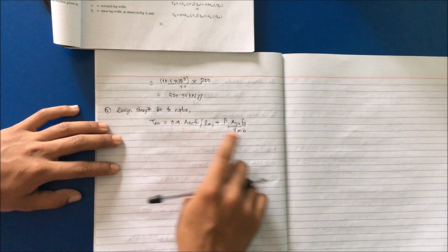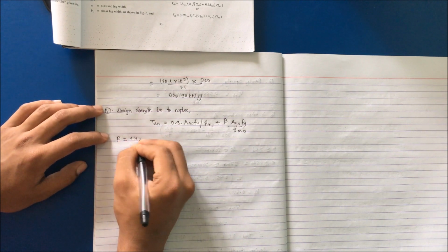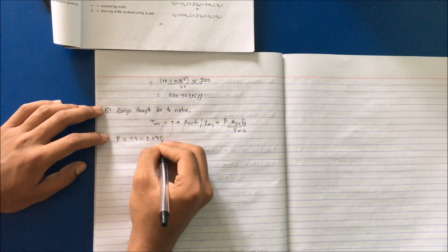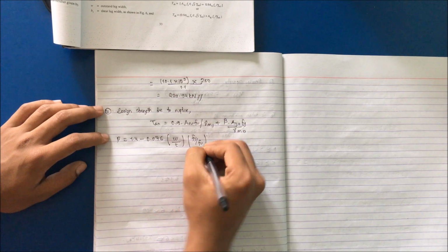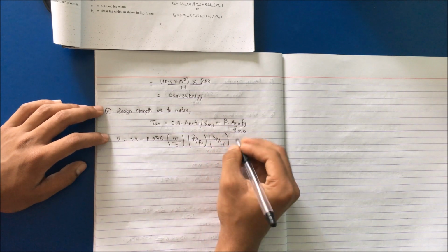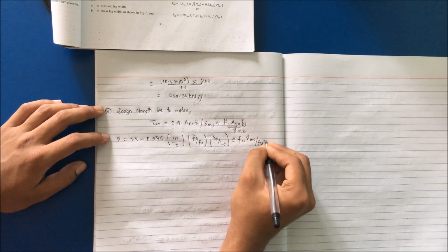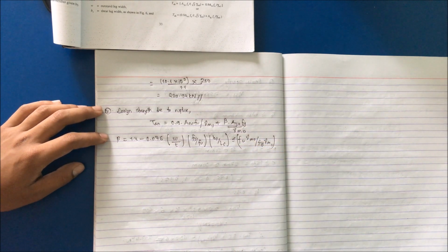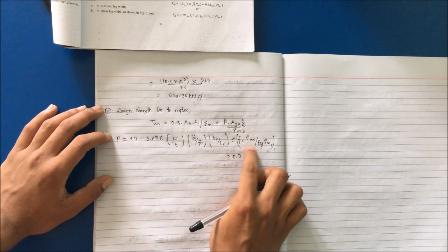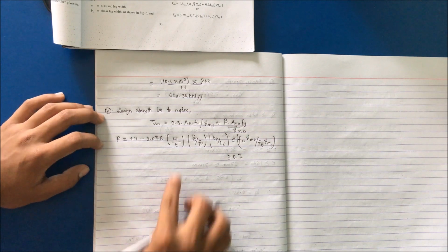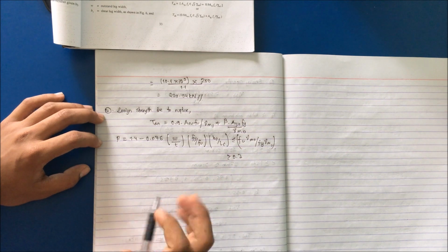Okay, so there are various new terms to us. The very first is beta, which is given by the formula: beta = 1.4 - 0.076 (w/t)(Fy/Fu)(Bs/Lc), which should be less than Fu gamma m0 / Fy gamma m1, and this value should be greater than 0.7 but less than this. So what are these terms? Wt, Bs, Lc. Okay, I will make clear.